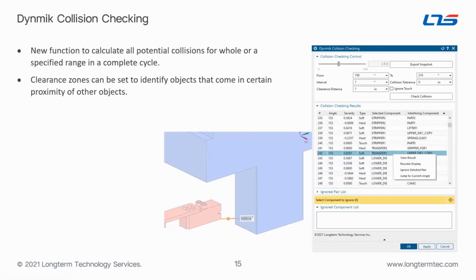So maybe you want to show some key step in a motion to someone, maybe internally or externally to the customer. You were not able to do that previously, but now you can. So we have that functionality: to whichever step you would go to, you can type in that number and then export that in a snapshot. So you can export that data out into a folder and open that out as the regular NX file. So you can do that with this program.